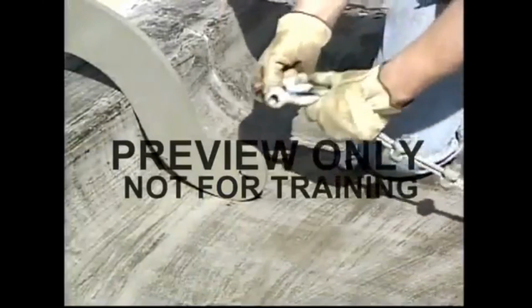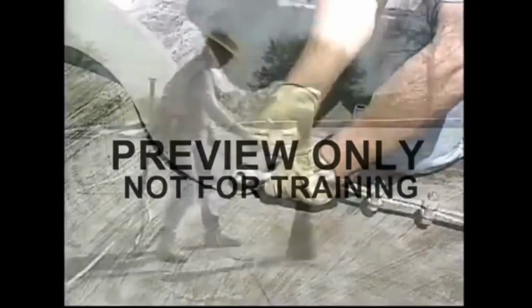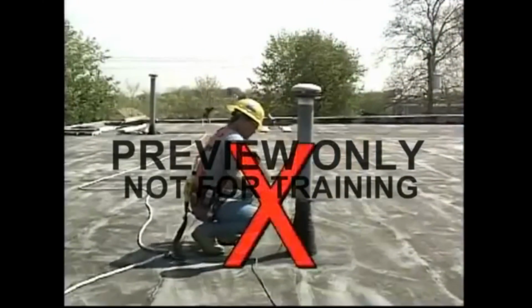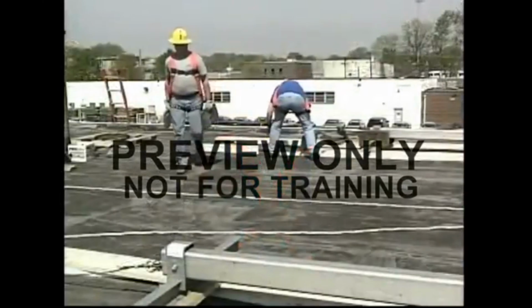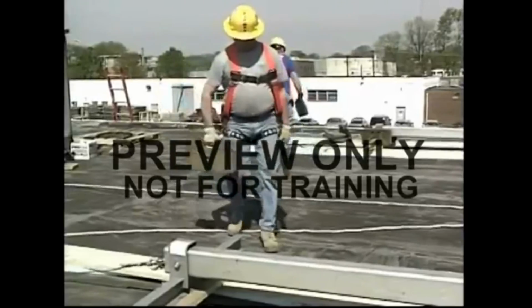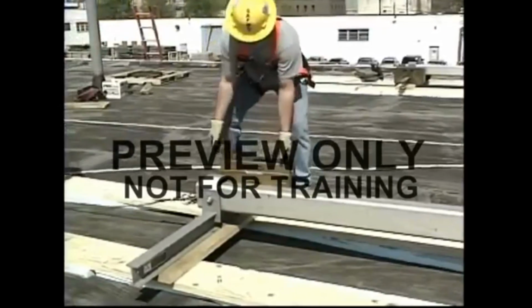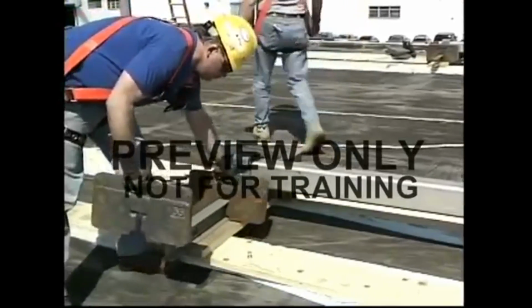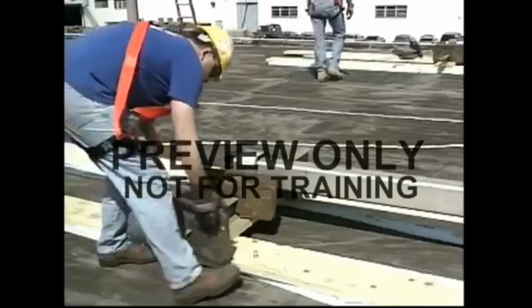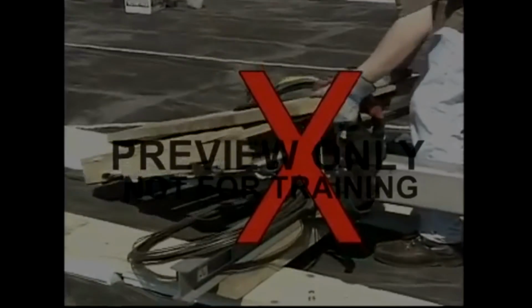They should be securely anchored to bearing supports, like a building's I-beams and girders, not things that could give way, like vents, pipes, or electrical conduit. To further stabilize the outrigger beams, counterweights should be attached. This creates a balance between the weight of the scaffold and the weight of the support beam. But be sure to only use weights that are designed specifically to act as counterweights. Don't use construction materials because other workers might think they are available for their normal use.